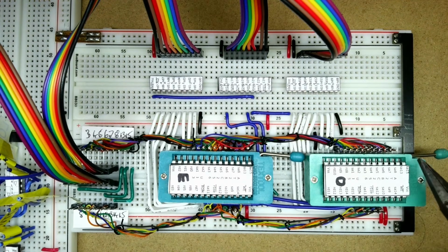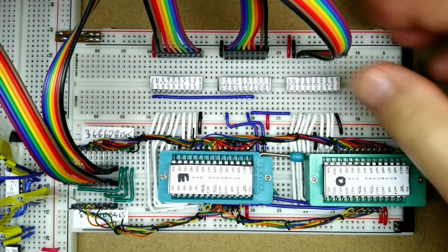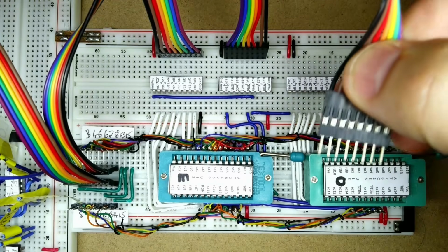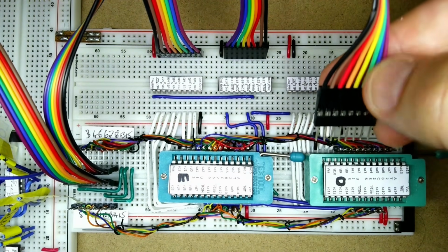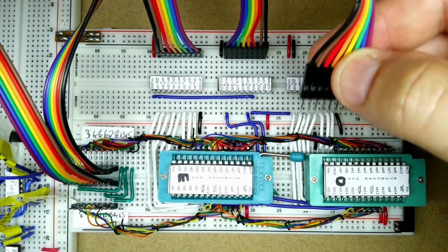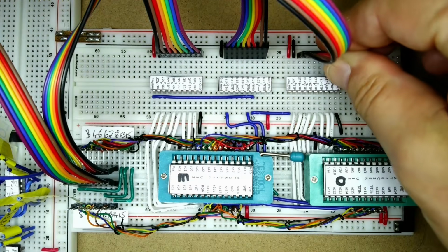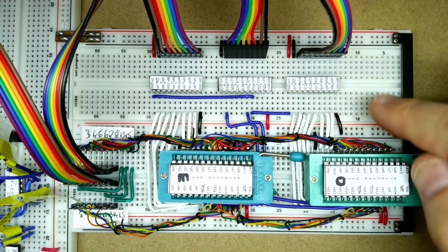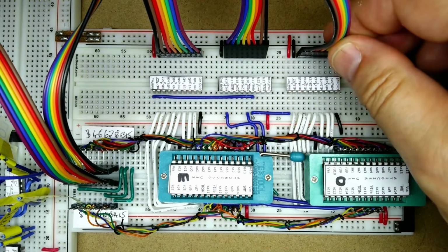So I have tested all of these with the continuity tester to make sure all these pins are connected across the way, so there aren't any loose connections there. I've also plugged in some 8-way DuPont cables, so these are like the individual pins, and then taken the single connectors off and put an 8-way shell on there, so that makes these a lot easier to plug in and out. So this is actually going over to the SD8 to SD15 on the data bus, way over on the other side of the board.